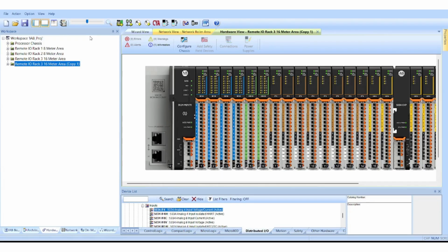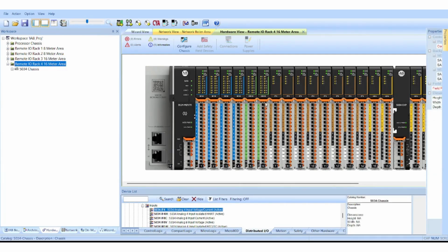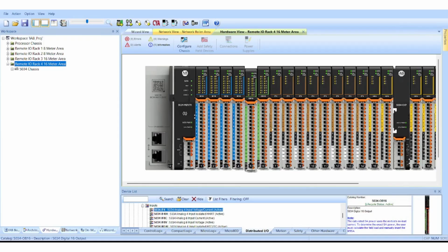One of the major advantages of a ring architecture is network resilience. Under normal conditions, communication operates through the ring according to the DLR mechanism. If a single network link is interrupted, the DLR architecture can provide an alternate communication path around the ring. This helps maintain communication between the connected automation devices and improves overall system availability. For a continuous process plant where communication reliability is extremely important, this is a significant advantage.